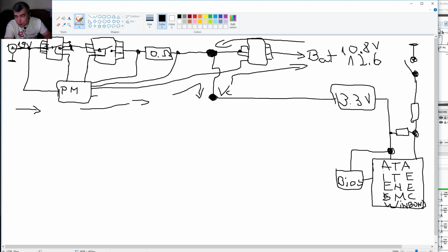As you saw in the videos, I make a short between two pins to start up the laptop. So if you push the power button, you start the laptop. That's exactly how the power button is connected to the motherboard. So you can make a short, it's not a problem. Most of the time you have a ribbon cable from here to the power button.